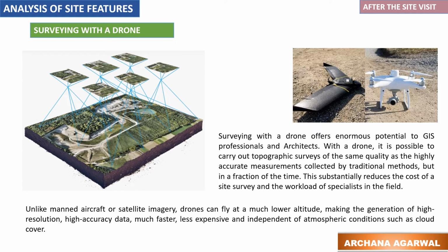During a drone survey, the ground is photographed several times from different angles and each image is tagged with coordinates. Photogrammetry combines images that contain the same point on the ground from multiple vantage points to yield detailed 2D and 3D maps. From this data, a photogrammetry software can create geo-referenced orthomosaics, elevation models, or 3D models of the project area. These maps can also be used to extract information such as highly accurate distances or volumetric measurements.